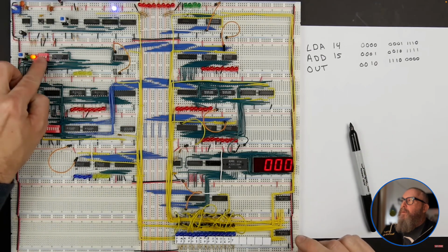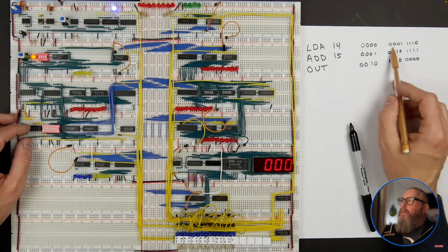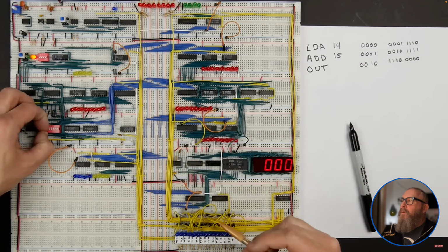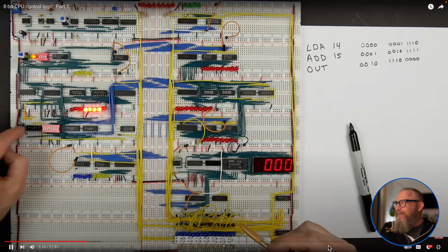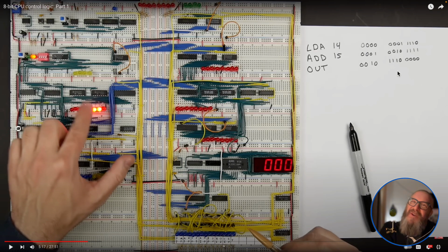If we want to be in programming mode here, we go to address 0, and we want to set this to 0001 1110. This is how the original programs were actually keyed in to a system. Before they had keyboards and a little bit higher level processing, they were doing it like this. Brutal. Talk about debugging problems. And we'll program that in. If you get just one of these wrong, the whole thing doesn't work.